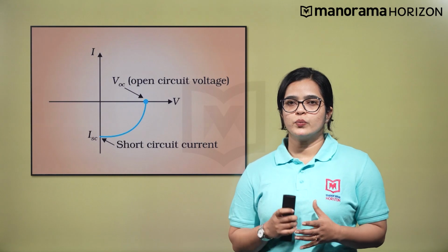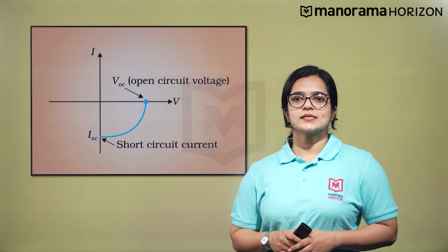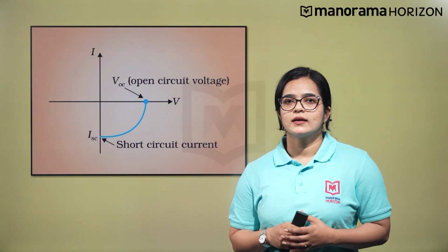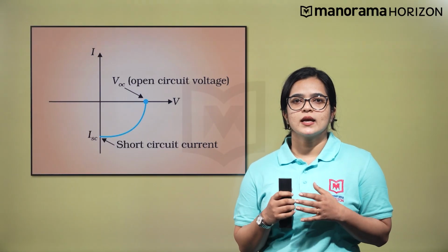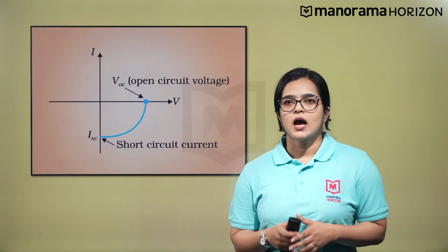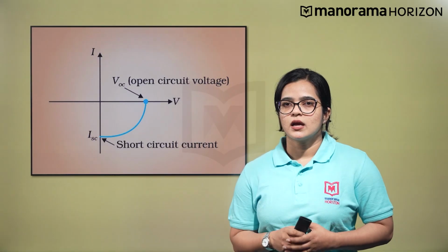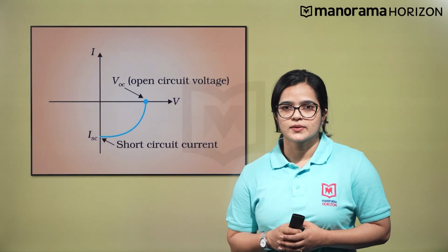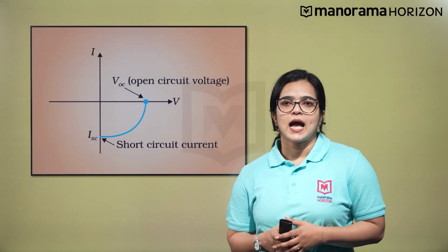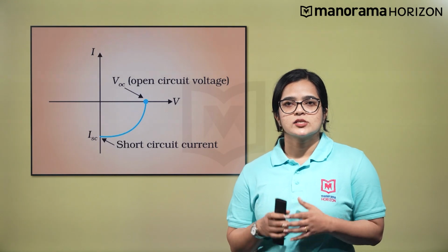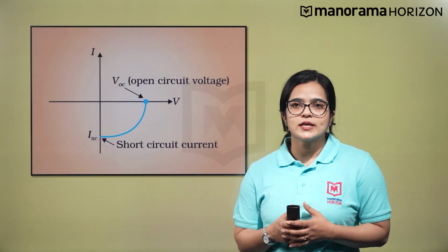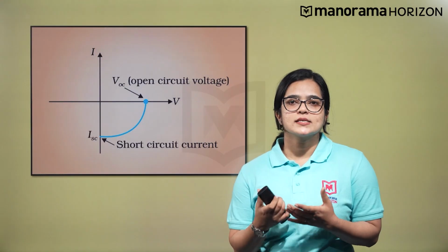Semiconductors with band gap close to 1.5 electron volt are ideal materials for solar cell fabrication. Some examples are semiconductors like silicon, gallium arsenide, cadmium telluride, etc. The most important criteria for the selection of a material for solar cell fabrication are the band gap, high optical absorption, electrical conductivity, availability of the raw materials, and the cost. Any light with photon energies greater than the band gap can be used for a solar cell, and sunlight is not always necessary. Solar cells have applications in transportation as solar energy is used in cars, solar powered calculators use photovoltaic cells, and another is the solar cell panels.